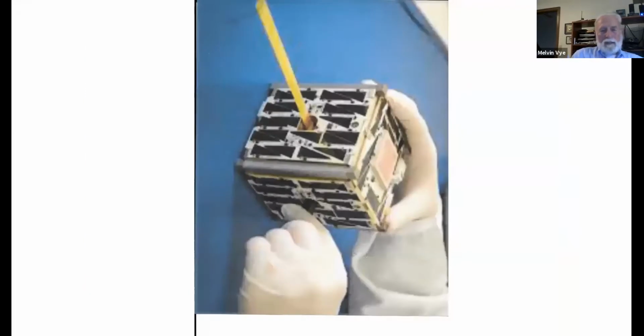If you want to know what a satellite looks like, here's an example, and you can see by this man's hand the size of it. This is what we call a 1U satellite. A 1U satellite is 1 unit, and a unit is defined as a cube that's 10 centimeters on an edge. For the metrically disabled, that's about 4 inches on an edge. So basically, these satellites have roughly about the same volume as a softball. So we have to put into that, of course, there's solar panels on all faces of the satellite, and we have to put in the transponder, the receiver, the transmitter, and some way of transmitting the received signal.